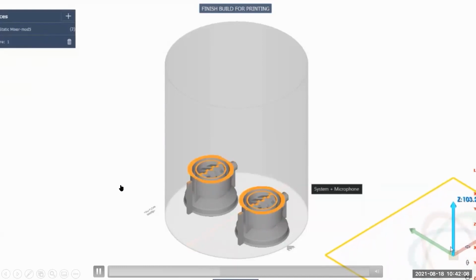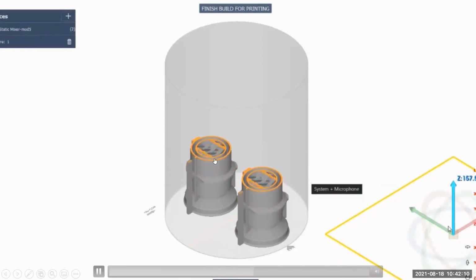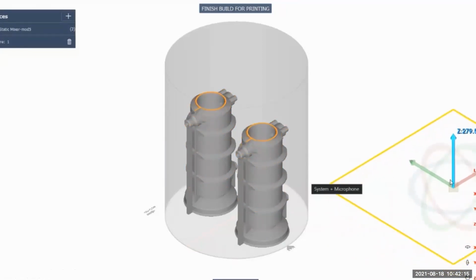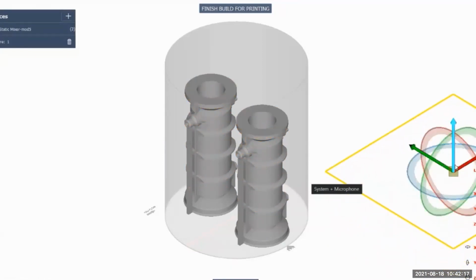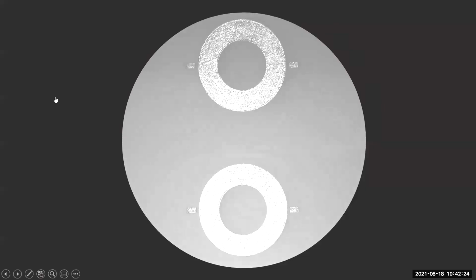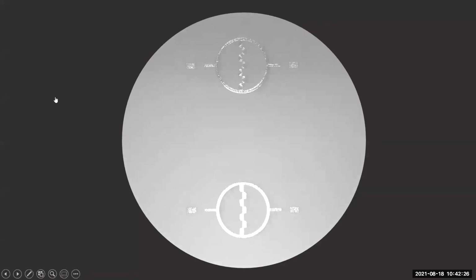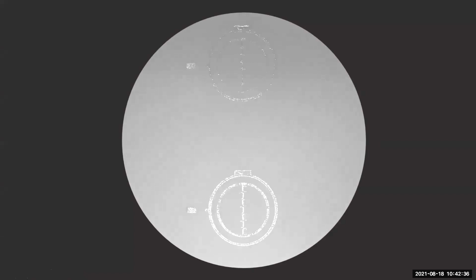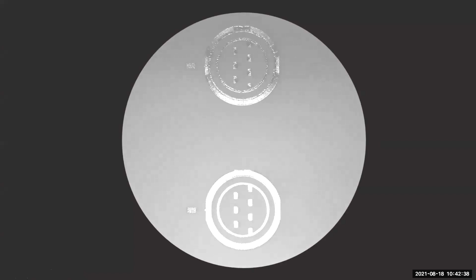As we go further up in the build, there are these ribs that come off the side of the part. Those build out at 30 degrees as well, without any issue. And then after it gets past the last bosses, it's pretty much home free from there. Then we have a video of what the actual build looks like from our height mapper images. On the outside of the main body of the parts at the beginning, there were 2 supports that we're building, but everywhere else you can watch and see that nothing has support building up to it.